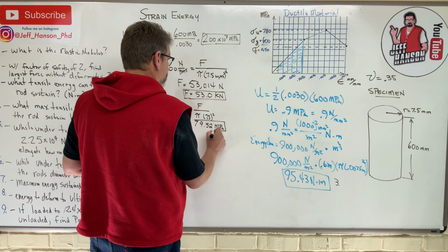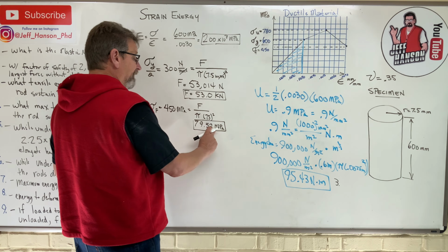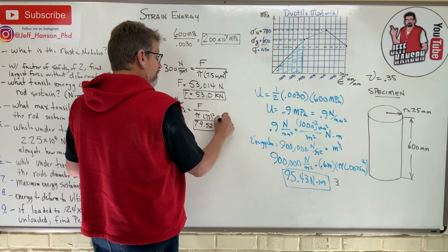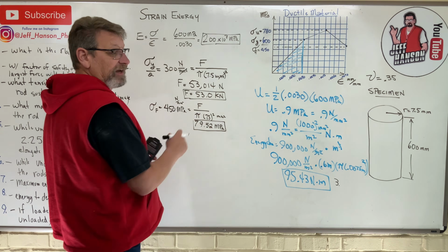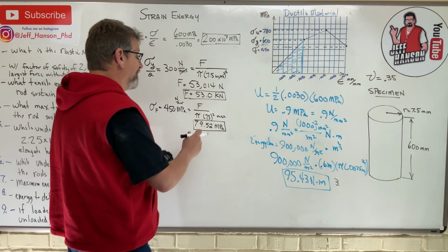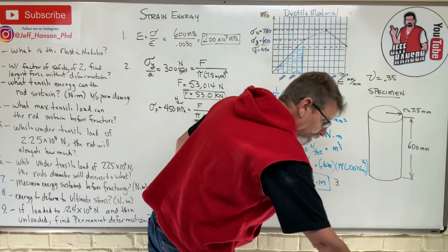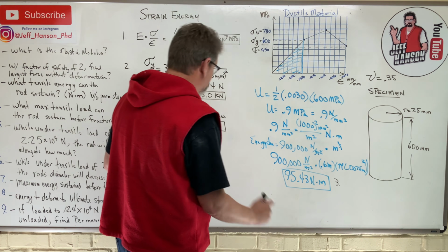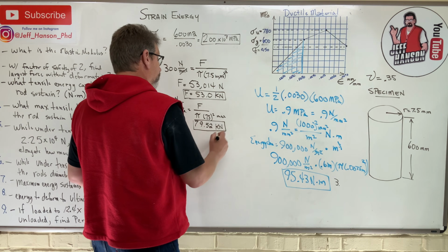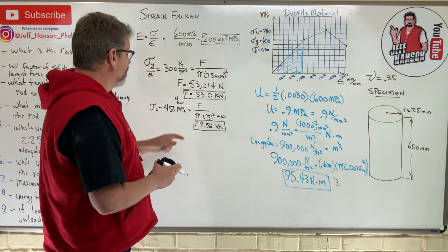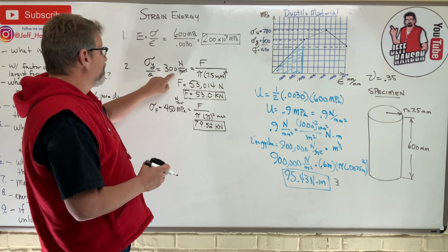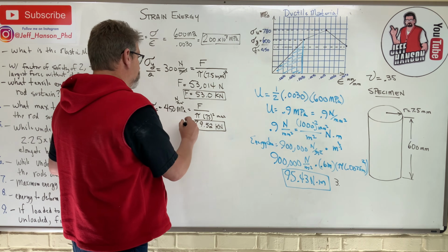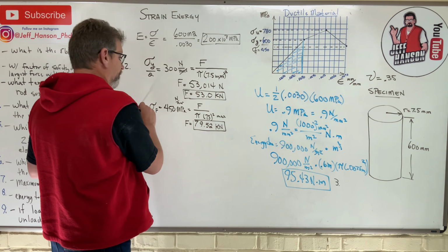Okay. Did I write megapascals? Is that right? This is newtons over millimeters squared. This is millimeters squared. So when I multiply that, the millimeters cancel out just like it did here. That's not megapascals, is it? No, sir. That's newtons, isn't it? And I moved the decimal over 3 places, so that's actually kilonewtons, okay? Just like we did here. And you're like, wait a minute, how come that's less? Oh yeah, this was 300 because of the factor of safety of 2, right? So this should be bigger, okay? So F equals that, and that is for number 4.